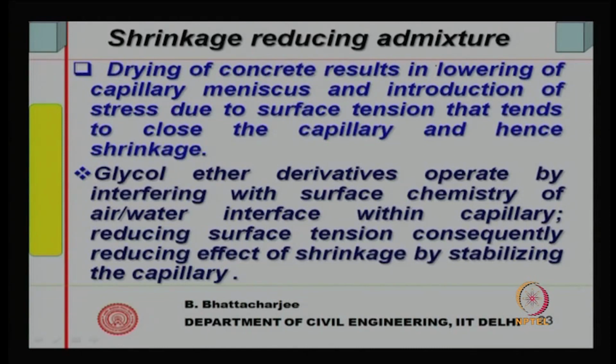These surface tension forces, which were at a balanced condition, have now changed because some drying has occurred, and they tend to close the capillary and hence cause shrinkage. The capillary will try to collapse under these surface tension forces.